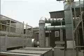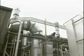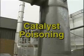These particles deposit on the catalyst surface, blocking access for the organic compounds. This is termed fouling. When low concentrations of particles are present, periodically cleaning the catalyst can restore more than 90% of its activity. Certain metals can react or alloy with the catalyst, permanently deactivating it. This is referred to as catalyst poisoning.